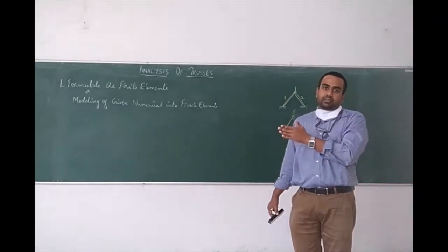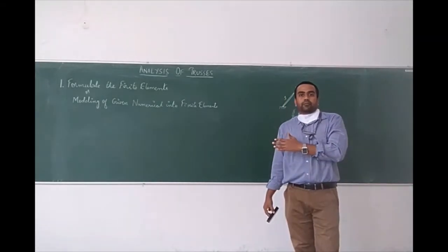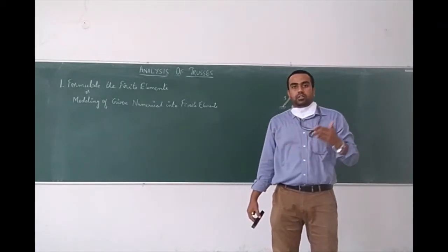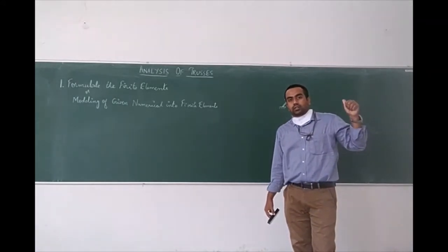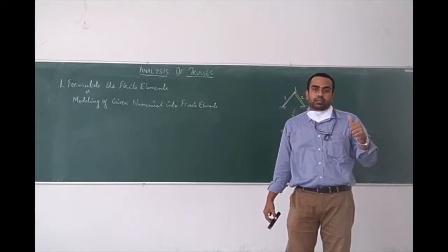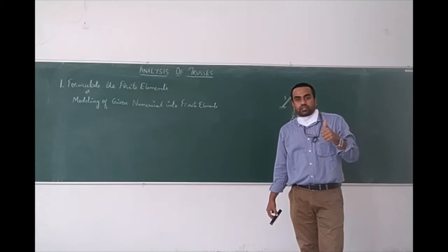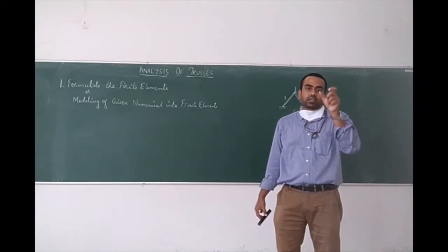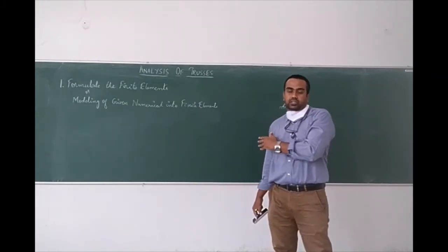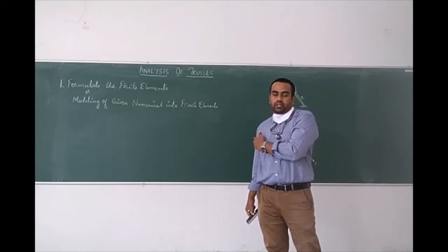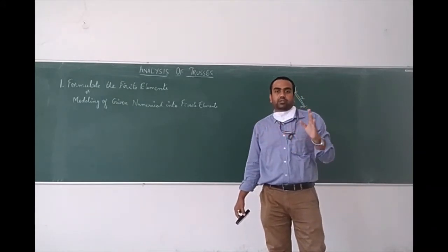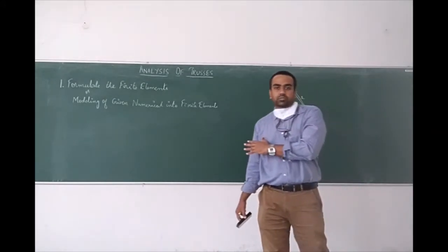After bars, with your syllabus in view, we don't go with the penalty approach method any further. We only go with the elimination approach. So remember, once you have done the equilibrium condition, you will apply the boundary condition and take up the elimination method. From the elimination method, the sixth step is you will obtain the displacement values. The last step, if it is related to structural members like bars and trusses, is to calculate the stress in those particular elements. So these are the only 7 steps that you come across in the finite element solution of problems.